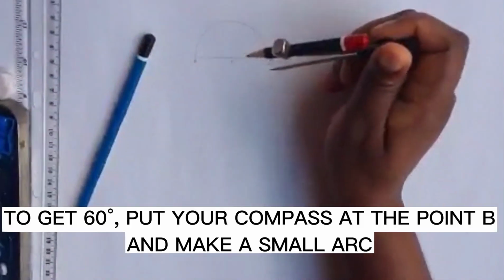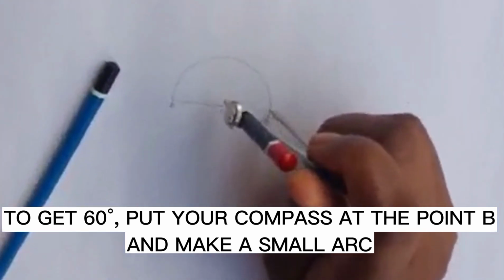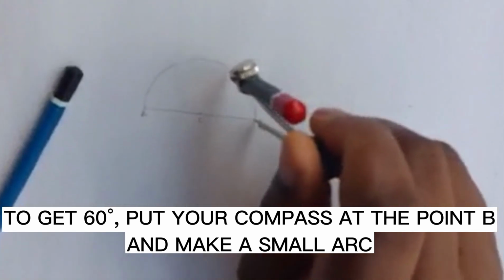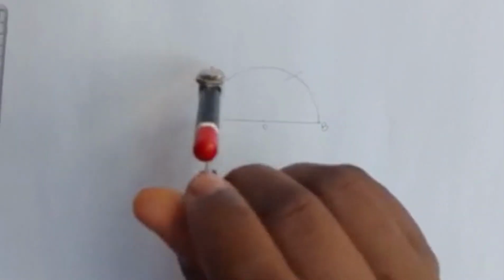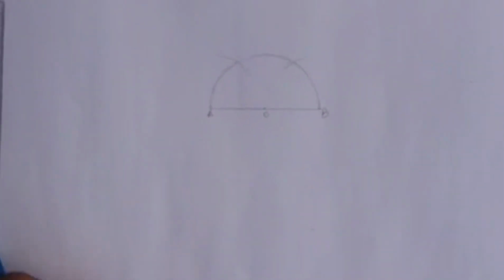Now, to get 60 degrees angles, let's start from 60 degrees. You put your compass needle right on the dot where your point B is, and you make a very small arc. Then to get another 60 degrees from this side, you put it right here, and then you just create an arc with the same radius that you started with.